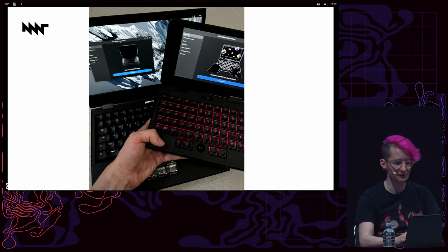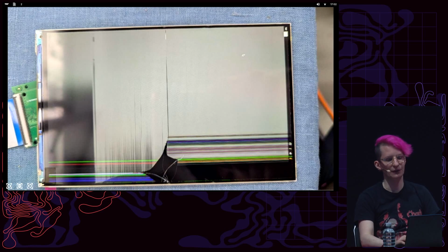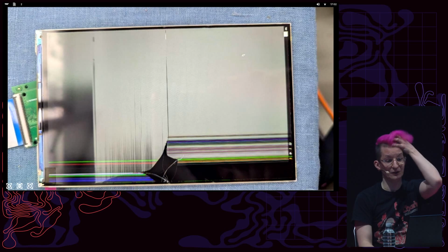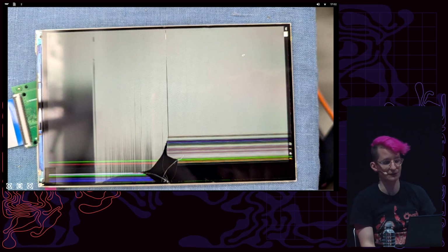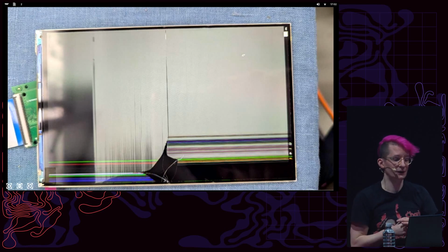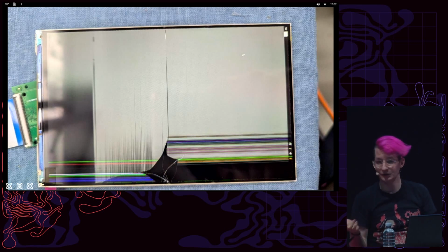Okay, I'm running a bit out of time, so I'll skip a few things about this. In production, we encountered several nasty obstacles. The biggest problem was that the display, while quite brilliant and well-known from the Nexus 7 version 2 tablet, was end of life, and I didn't realize that most of the existing stock has quality issues. So we couldn't get this display fresh from the factory, and whenever we ordered batches from several suppliers, we had to QA test them and throw a lot of the displays out.